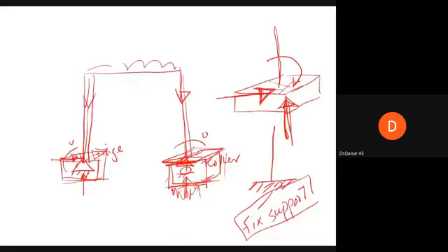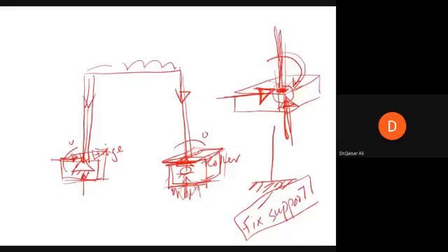but for it to act as a fixed support, the bending moment resistance will be provided by the column and the foundation, at the contact point between the column and the foundation. This shall be designed such that enough reinforcement is provided at the column and foundation interface, so that there is bending moment resistance. The column should not fail at the interface of the foundation.